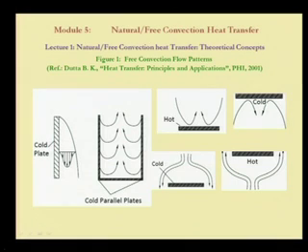Similarly, in the case just opposite to this, the bottom face, the lower surface, is the cold surface. So, what will happen? Once fluid elements come in contact with this cold surface, they will become heavier and try to come down, and then some other fluid elements which are hot will try to take these positions. Therefore, the circulation will be opposite to the previous one.